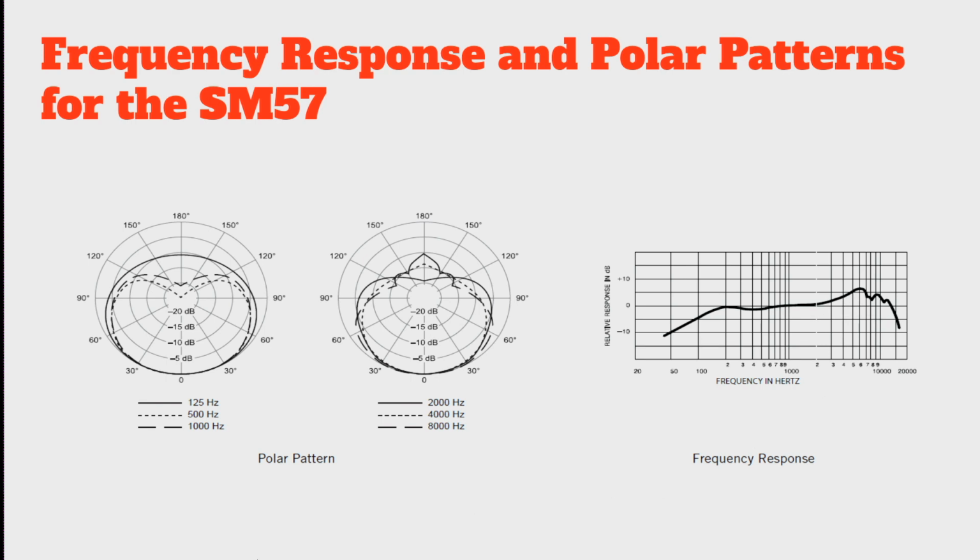Now, we might imagine, as we're looking at this microphone, that since it doesn't respond equally at all frequencies, that could be a bad thing. In reality, that's not really true. It's just a characteristic of the microphone. There are times where we in fact want a microphone that represents all frequencies equally. There's also times that we want a microphone that exaggerates certain frequencies. We can think about the responsiveness of the microphone as sort of having an EQ on the microphone. And if we're going to end up EQing and boosting certain frequencies when we record or when we're playing back through a sound reinforcement system, why not use a microphone that does that for us at the capsule or sort of within the signal flow of the microphone.